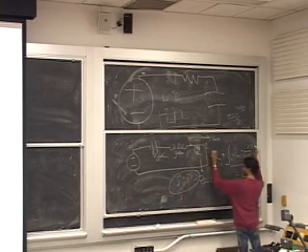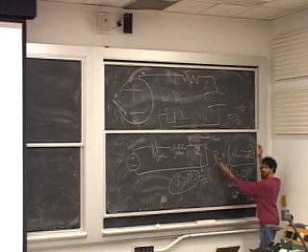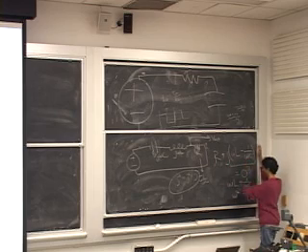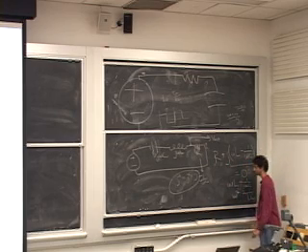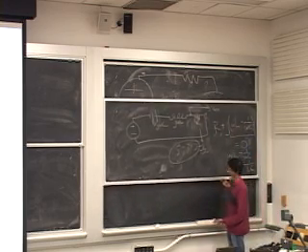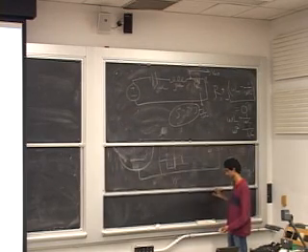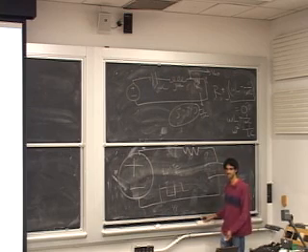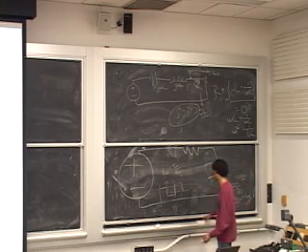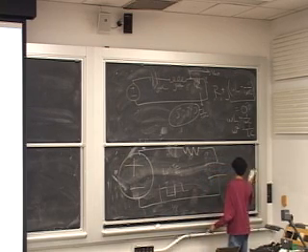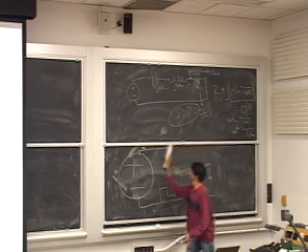Okay, so our net impedance is still this, R plus j omega L minus j over omega C. Now, this implies that there's some frequency at which I can minimize the impedance to just R, which is kind of cool.